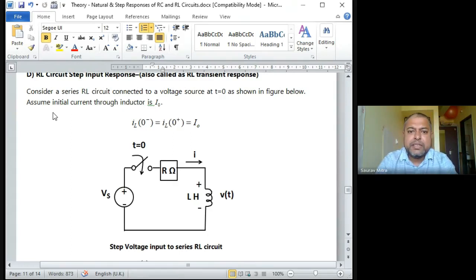They are the reconstructed waveforms. Now you find that if I take 200 hertz sampling frequency, some kind of odd waveform comes instead of a sinusoid. It doesn't look like a sinusoid. If you take 0.001, that is 1000 hertz sampling frequency for a 100 hertz signal, then you might find it looks somewhat like a sinusoidal waveform.